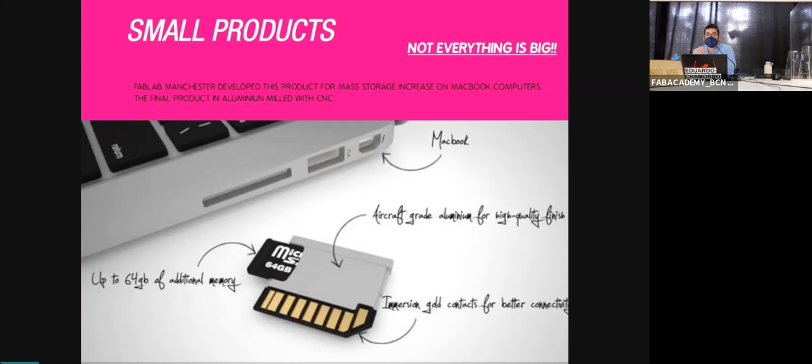This happens with almost all the aluminum parts. And you can do it with a really, really accurate and small finishing. Basically, this is determined by the size of the end mill, how accurate you want to do your cuts. For example, this is a small product showcase, an SD card holder for expanding your memory on your computer. You can cut aluminum, yes, but when prototyping your design, you never cut the aluminum part first.